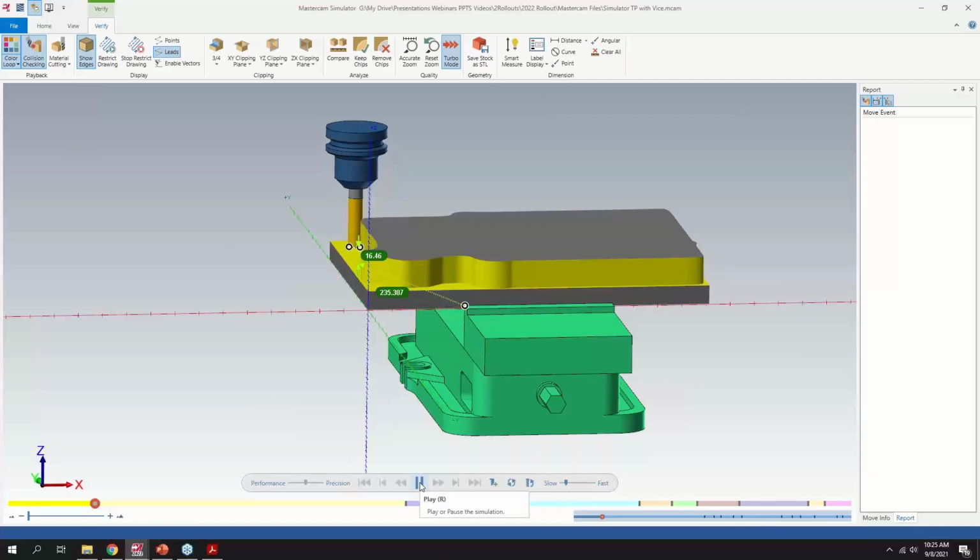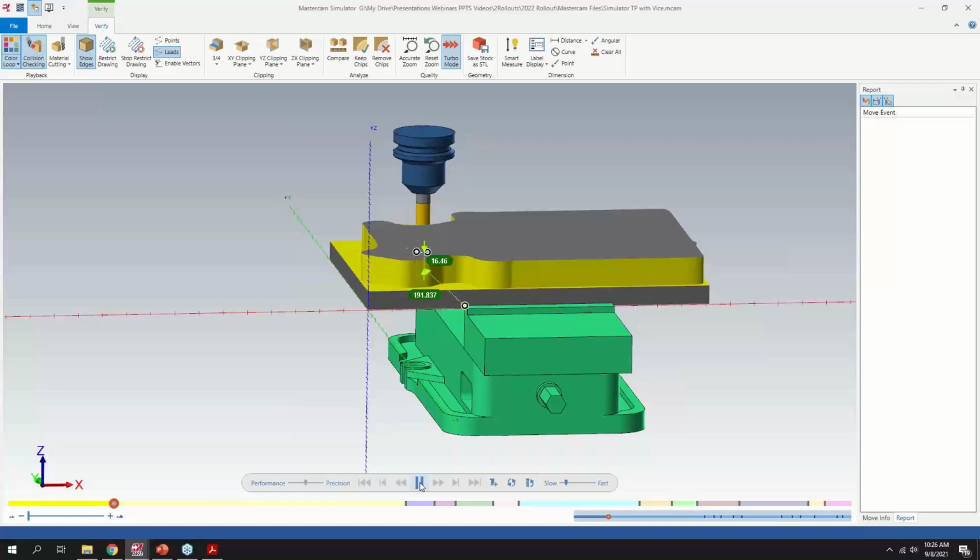And I might just add, I had a student in here while we were taking a lathe class where he asked, can we measure the distance between the part and the stock or in the jaws for a lathe? Well, you can't measure that very easily in Mastercam. In the Verify, since those chuck jaws take actual shape, you can measure it within here in the Verify. Oh, right. That's a good use case.